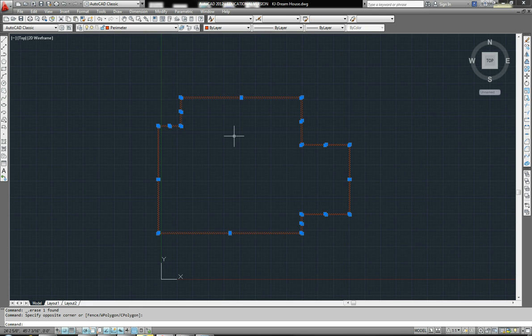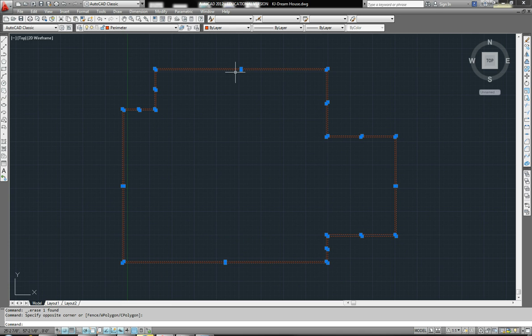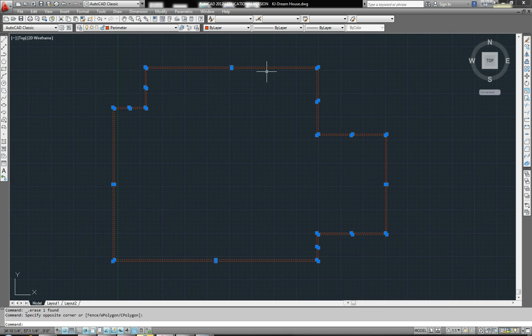If you have any short line segments, any non-closed segments, meaning if these lines aren't a closed perimeter, the program won't generate the roof properly, and I'll send the file back to you and tell you that you wasted my time. So again, this is the most important step. Make sure that every line is continuous from one point to the other, meaning corner to corner, and there's no short lines. So every line is one line from one point to the next. If you have shorter lines or line segments, go back and delete them and make them one line from point to point. Once you've created this, you're ready to send me this file.